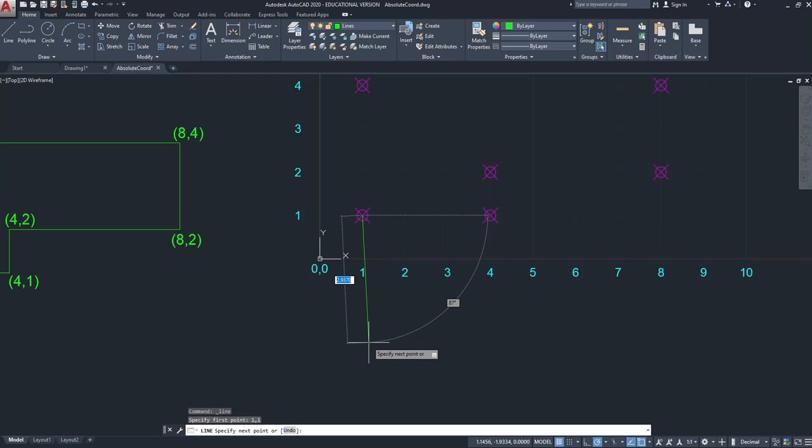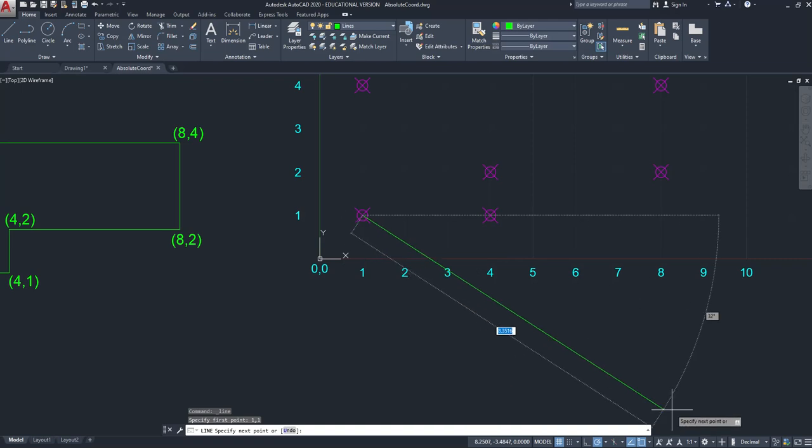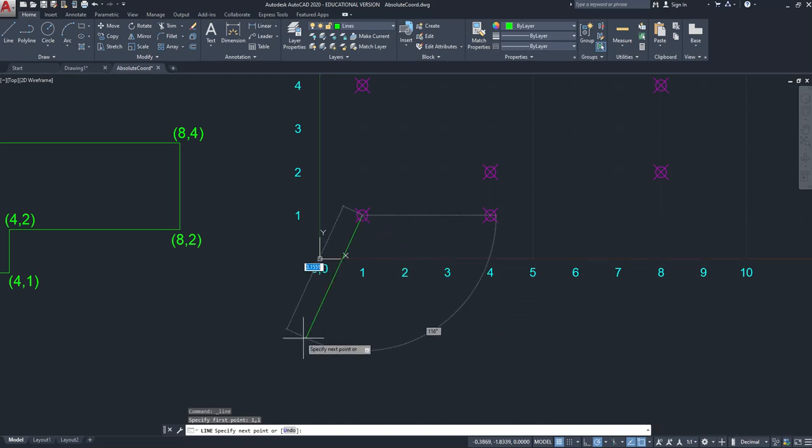Right now our current unit is decimal, but you will all change yours to architectural and we'll work in that format for most of the semester. So the inch is the default unit in AutoCAD. So if I type 1, enter, 1 inch is going to be entered, or whatever default unit is current here. So in this case, it's decimals, okay.